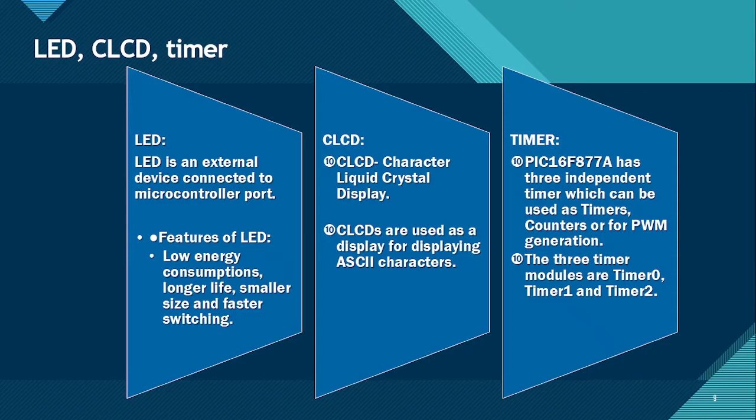Timer 2 has a period register. The period register stores a certain value, and the timer will count from 00H to the value of the period register. It will go into overflow mode once it reaches this period register value.